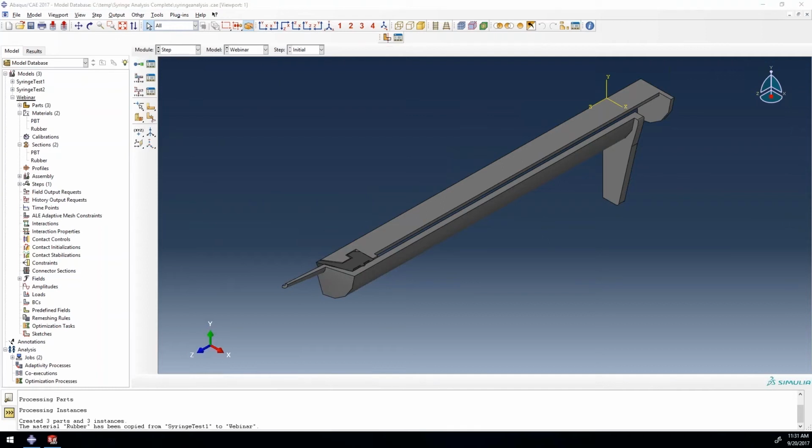So this brings us to the step module. So steps are definitely one of the first things that is going to differ a lot from a SOLIDWORKS simulation that you'd set up. In Abaqus, you can essentially break up the problem history into these different steps. A step is a convenient phase of the history. It contains a discrete set of boundary conditions with a defined analysis procedure. So this analysis procedure can be changed between studies from static to thermal to dynamic.